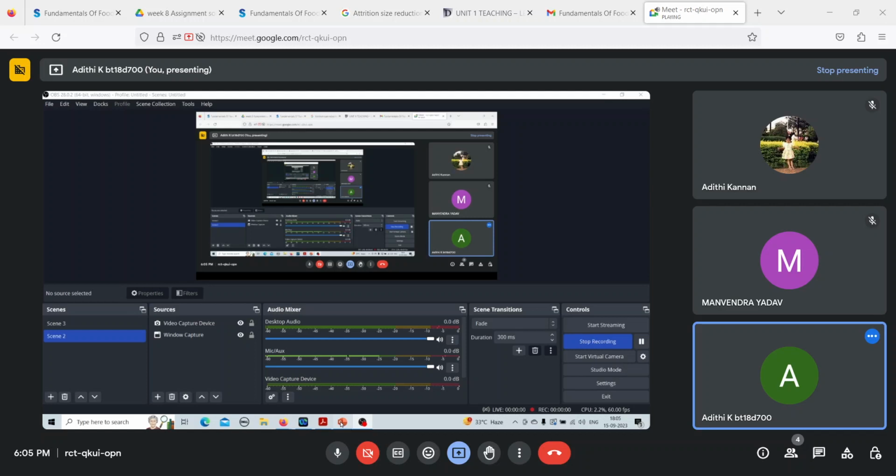Question 17. A material is milled from 15 millimeters to 2.5 millimeter using an 8 kilowatt motor. What size motor will be required to reduce the size now to 0.2 millimeter using Kick's law? So given here, for the first case scenario, XF is 15 millimeter, XP1 is 2.5 millimeter, and the energy for that particular size reduction is 8 kilowatt.